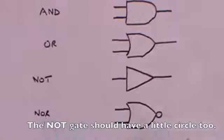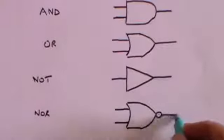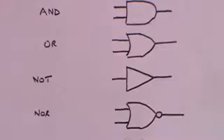So it's a NOR version of the OR gate. And what this means is that you only get a positive output if both of these have no voltage in the input. So if there's no voltage here and no voltage here, you get a positive voltage out. But if either or both of these have a positive voltage, you get nothing out here.